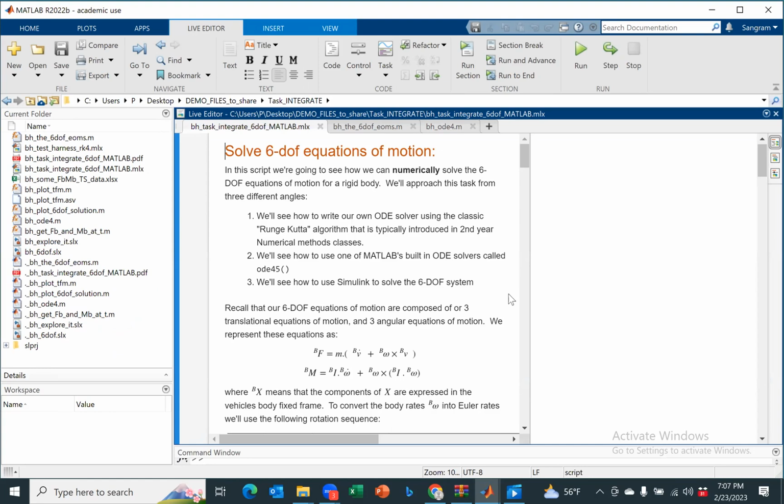And the second equation, remember, the inertia tensor multiplied by the rate of change of angular velocity, which is angular acceleration, plus omega cross I times omega. I derived this. Same equation, no matter what flight vehicle it is, you will have these equations. 3 equations for forces, 3 equations for moments.